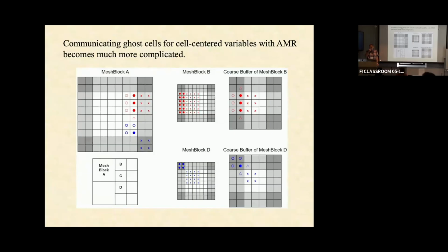Yes. Is there a limit of the refinement level between adjacent blocks? Yes, good point. And I failed to say this, but in almost every code I'm aware of, there's a limit of a factor of 2 between the mesh block boundaries. And that's mostly because much more than that, and then your solution is completely dominated by the interpolation errors you need to prolongate and restrict.